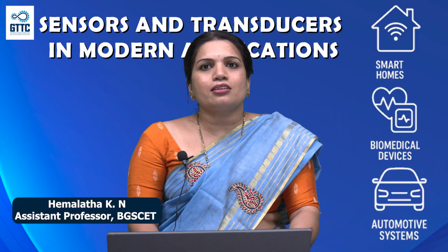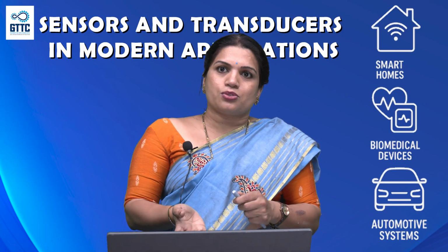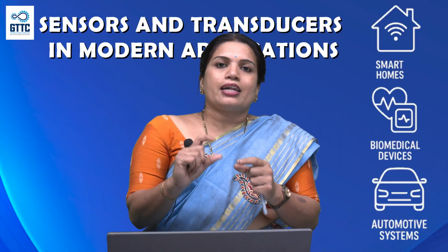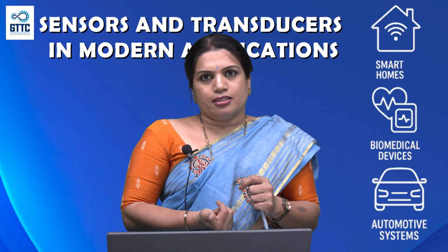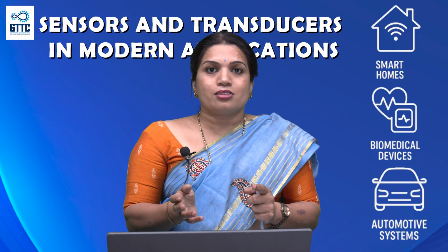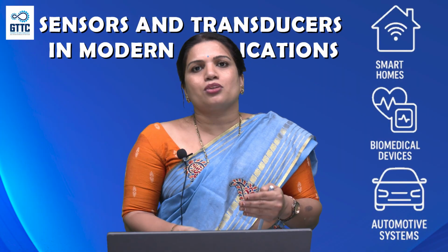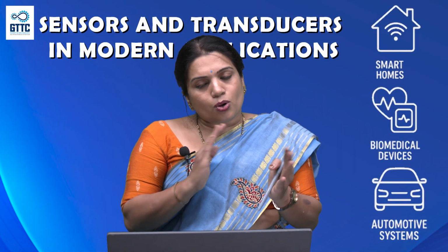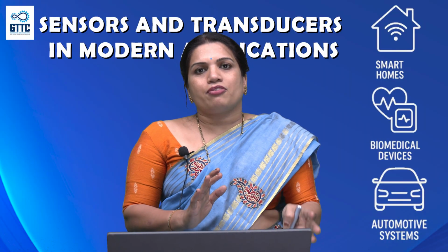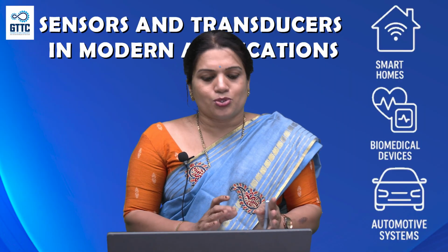Is it a sensor? Yes, it is a sensor. Is it a transducer? Yes, it is a transducer. Why is it a sensor? Because a thermistor senses the temperature and it will be converted to an electrical signal. Is it a transducer? Yes, it is a transducer because heat energy is converted to electrical energy. We can tell that both are correct because both are transducers, coming under the umbrella of transducer. It works on the input side, that's why for sensors I call that an input transducer.